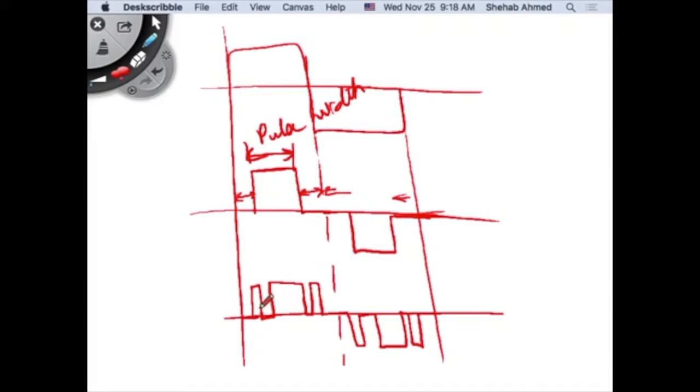Instead of rising suddenly, like this is a 0 and then a sudden rise in the value, here I have a sudden bump in the average value of the waveform, and then another bump, but with a bigger duration, right? So it seems it's closer to a sine wave, which rises slowly to a higher value. This area would have a small average value, this area would have a higher average value, then a small average value, then 0, right? So you're closer to a sine wave, right?